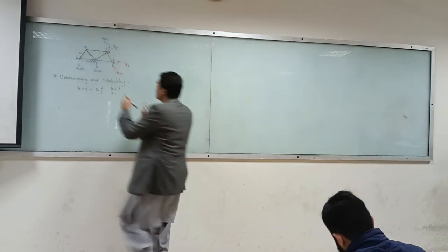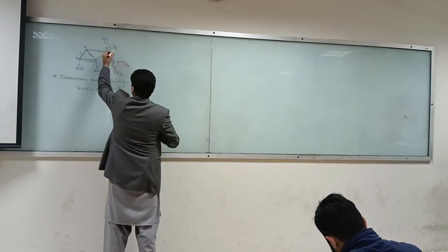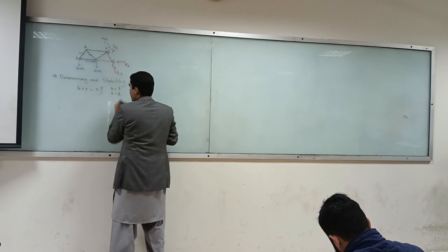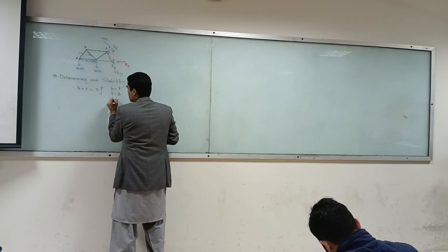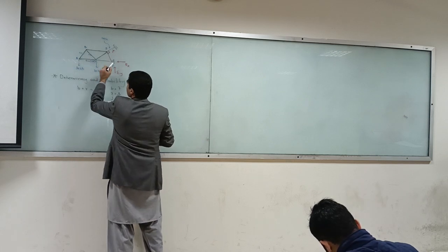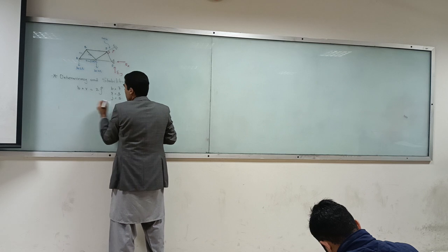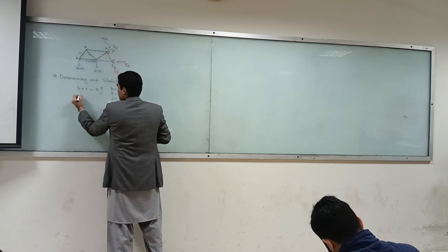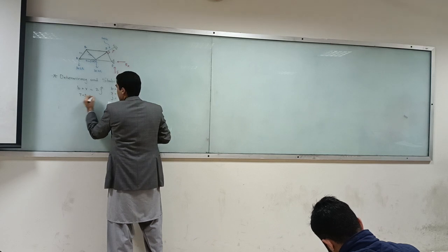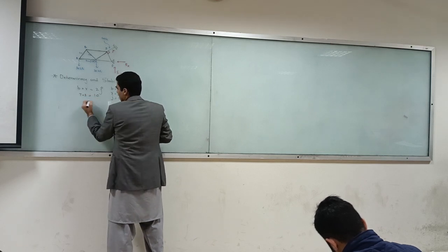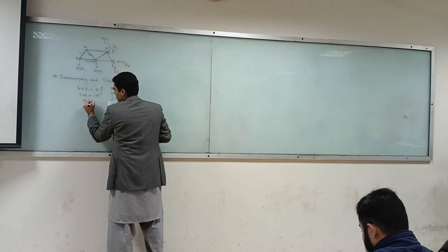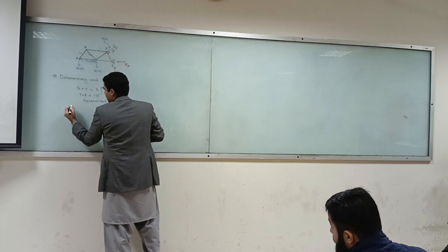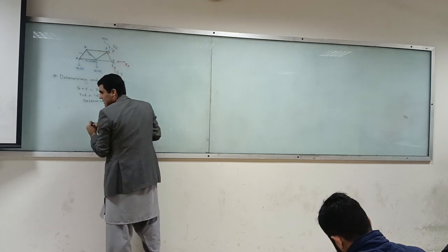So we have only T over here. So this is only T. So the reactions are 3, and the joints are how many? 1, 2, 3, 4, 5. So we have 7 plus 3 equal to 10, and this is determinate.